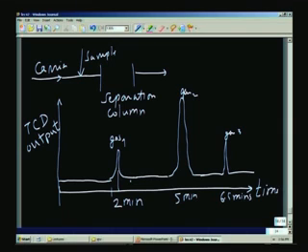concentration is present. Of course, the gas concentration depends also on the thermal conductivity ratio. So, we have to correct for the thermal conductivity of the particular species, or we can do the following. We can calibrate the instrument with different mixtures with different gases and find out what is the output for a particular gas, and accordingly we can find out what is the scale factor for that particular gas and then introduce that in the quantitative interpretation of the signal.